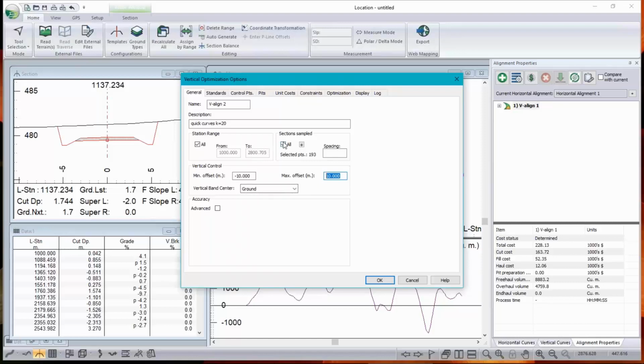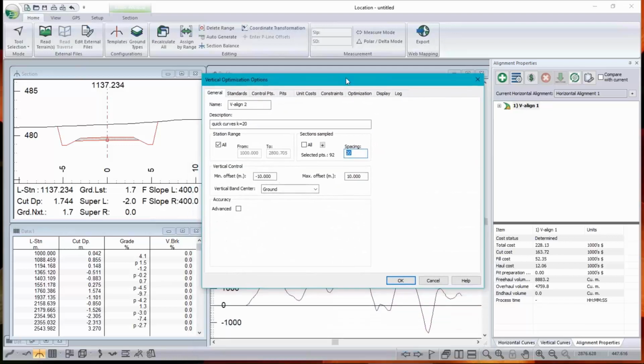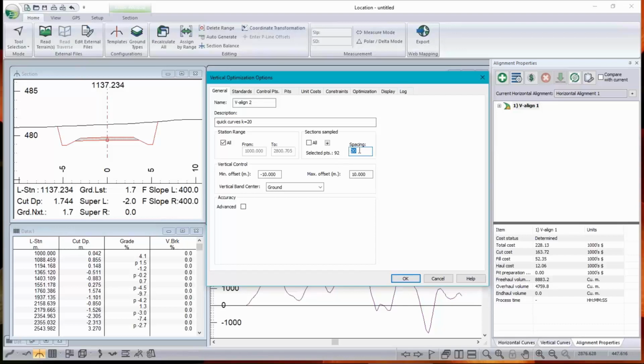We're going to cut the road up into a bunch of sections, and I'm just going to pick a section every 20 meters. Again, we'll come back to whether or not this kind of sample spacing is reasonable. I've done this before, so I know 20 is good, but basically the sample spacing depends on how bumpy your ground is. If you've got nice smooth ground, you might get away with a longer sample spacing. The sample spacing determines how many points we have to calculate, and that costs you a bit of time later. So, okay.